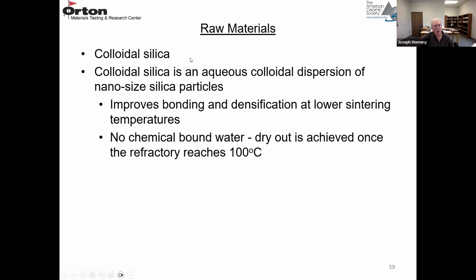And then the colloidal silica is a dispersion of nano-sized silica particles in water. So these fine silica particles are very reactive, so that they improve the bonding and densification because they sinter at low temperatures.